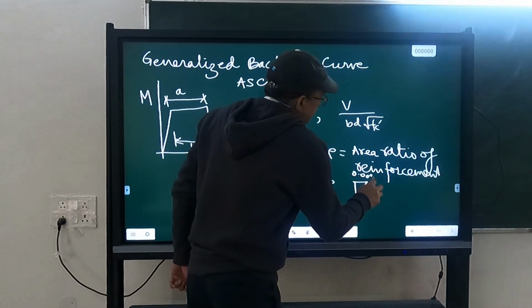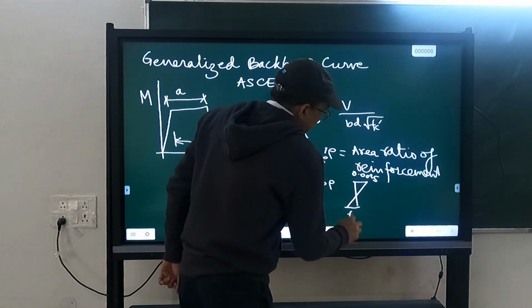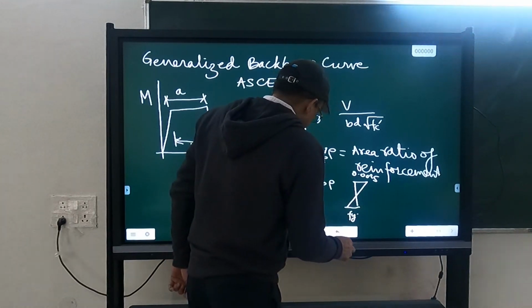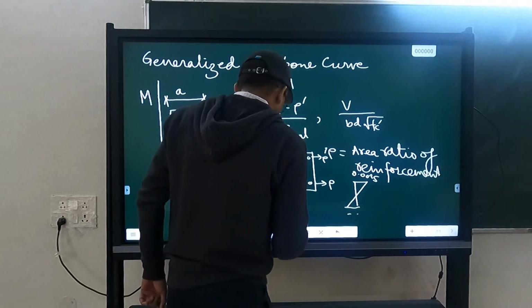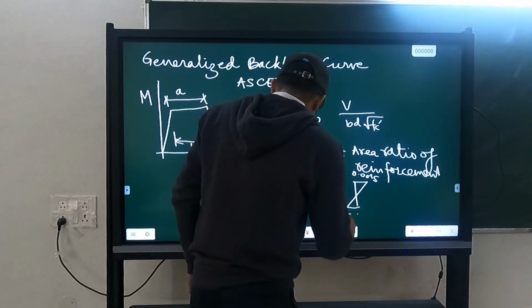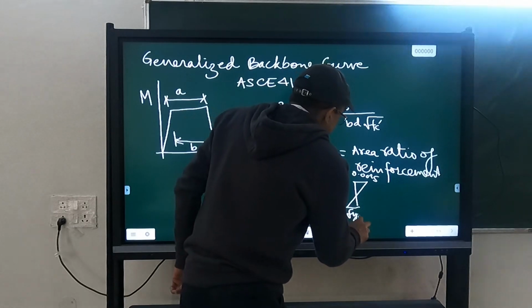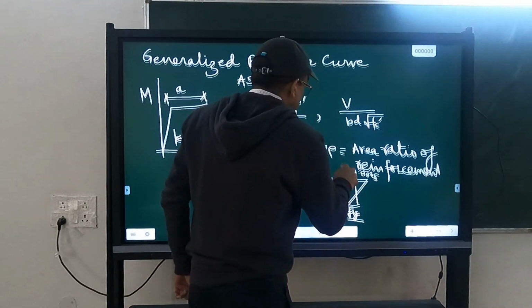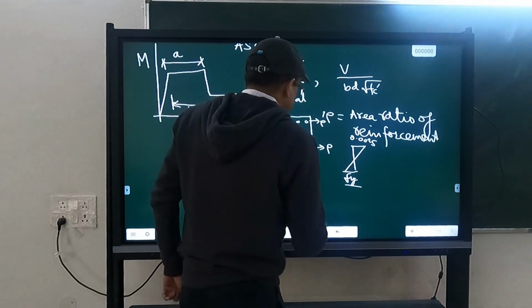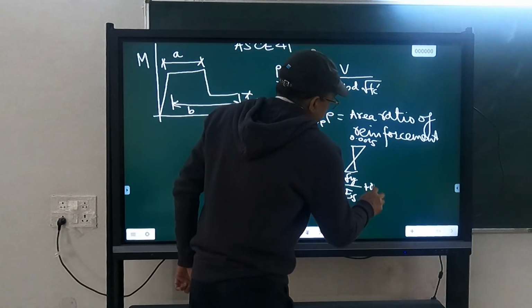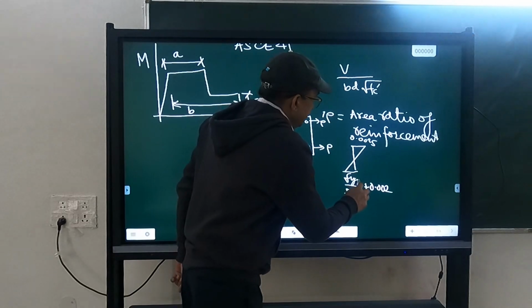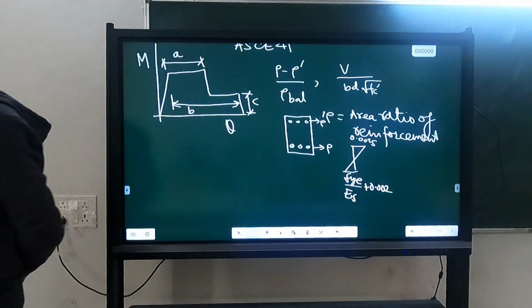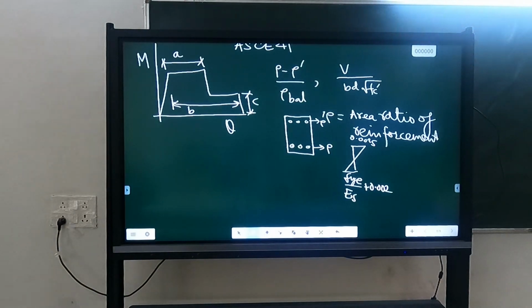So you take this as 0.0035, divided by fy over Es plus 0.0035, and so on. In our case, when we are using expected values, you can take it as expected. So this will give you the balanced failure reinforcement.